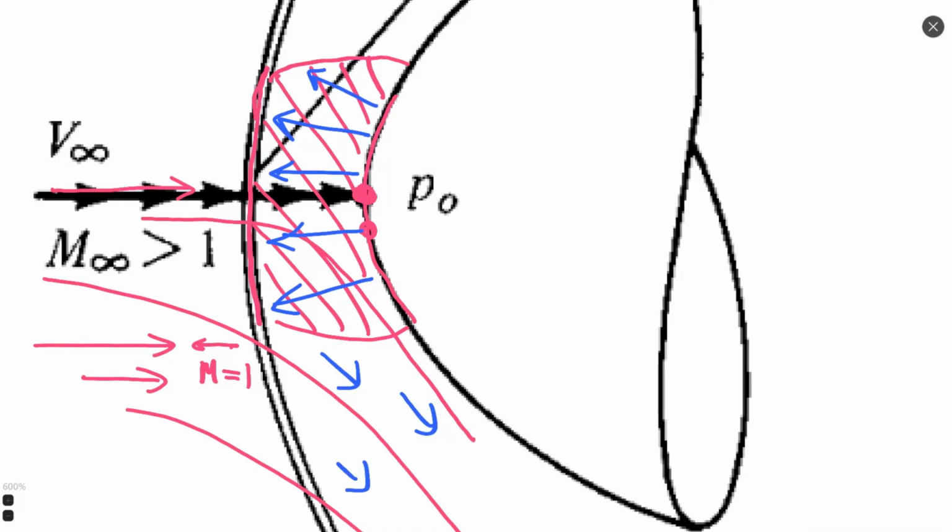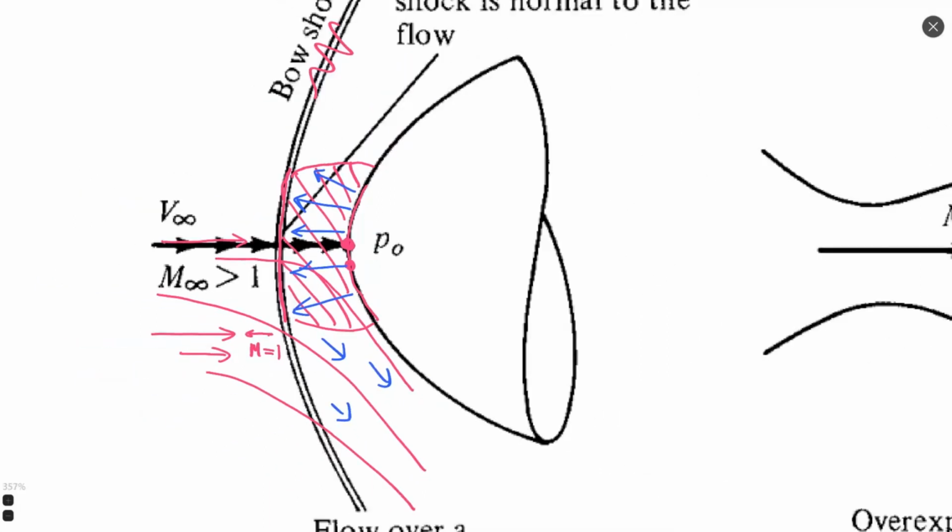Actually, the shock wave by itself is a huge number of accumulated pressure waves, or accumulated sound waves, that are reflected from the body and generated by the body. And the shape of the shock wave depends on the shape of the original body. It's important in which direction the flow is reflected. So the shape of the shock wave usually repeats the shape of the body. It's not very simple and not very linear, because the theory of flow is not linear. But in general, it's like this.